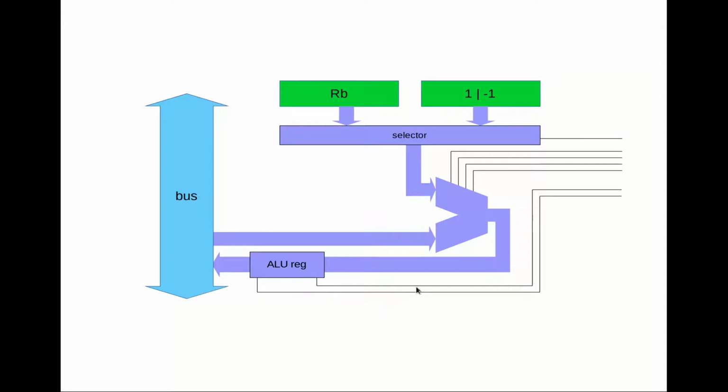Now, in addition to providing the result of the calculation, which is then latched into this register, the ALU is also going to provide a series of flags. And the flags are things like the carry flag or the zero flag, or they're going to give us some extra information about the calculation, or in fact about the value, which is here.